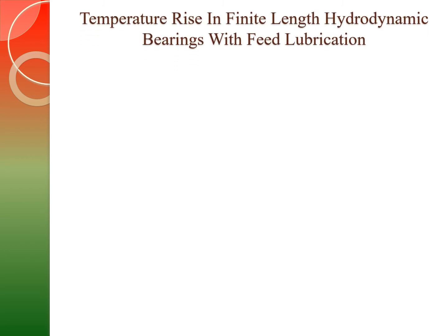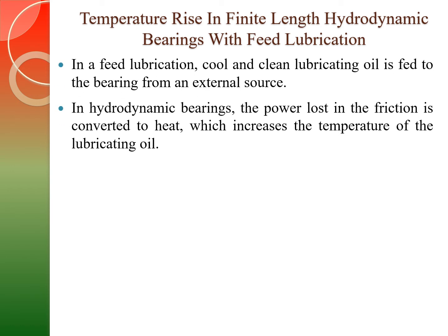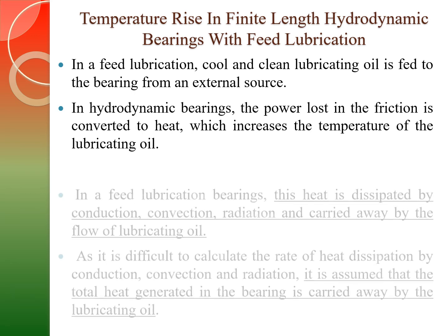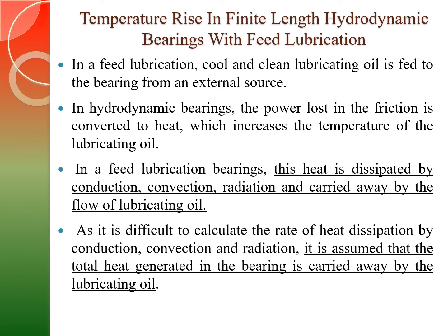Next, in design consideration, temperature rise in finite length hydrodynamic bearings with feed lubrication. In feed lubrication, cool and clean lubricating oil is fed to the bearing from an external source. In a hydrodynamic bearing, the power lost in friction is converted into heat, which increases the temperature of the lubricating oil. In feed lubrication bearings, this heat is dissipated by conduction, convection, radiation, and carried away by the flow of lubricating oil.